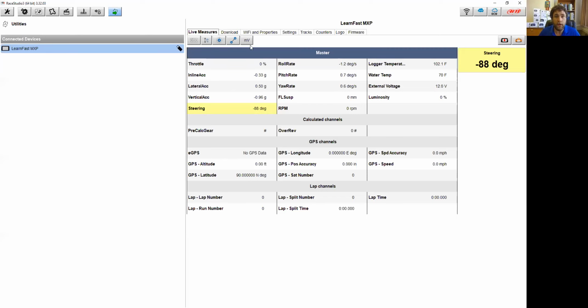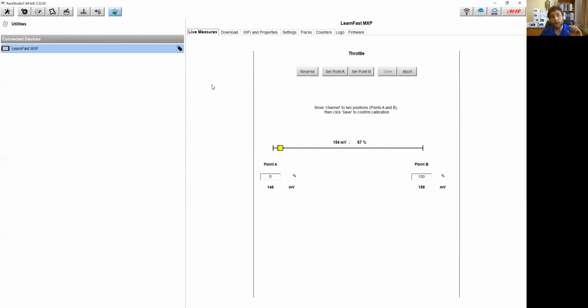What we're going to do is we look and we see our calibration area, and we're going to say throttle position. Throttle position is one of the easiest sensors to calibrate, because all we really need to do is set 0. I always think 0 to my left and 100% to my right. Oftentimes I climb in the car, or if it's a race car with big NASCAR bars and it's hard to get into, one of my tricks is I go find the broom that the team uses to sweep up, and I can get the throttle pedal by sticking the broom in the car and pushing it down so I don't have to climb in.